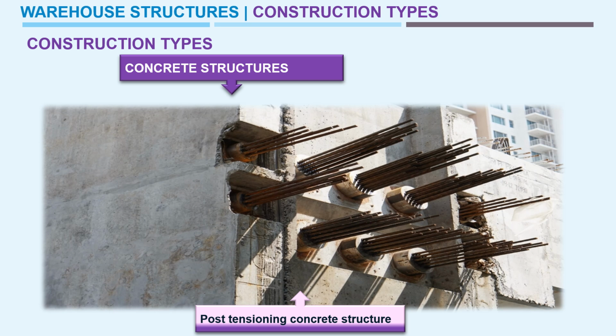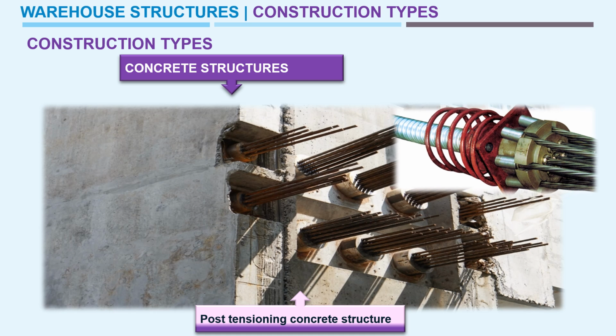Also the post tensioning can be classified into two. One is unbonded, another one is bonded post tensioning. So this is a coupler with the tendons. This is to be applied in the slabs while casting at site itself, and later, before the shuttering, the tension is to be released, so that the tendons will provide more stress on the concrete, so that the concrete will regain its strength. So this way this post tensioning process can be done.